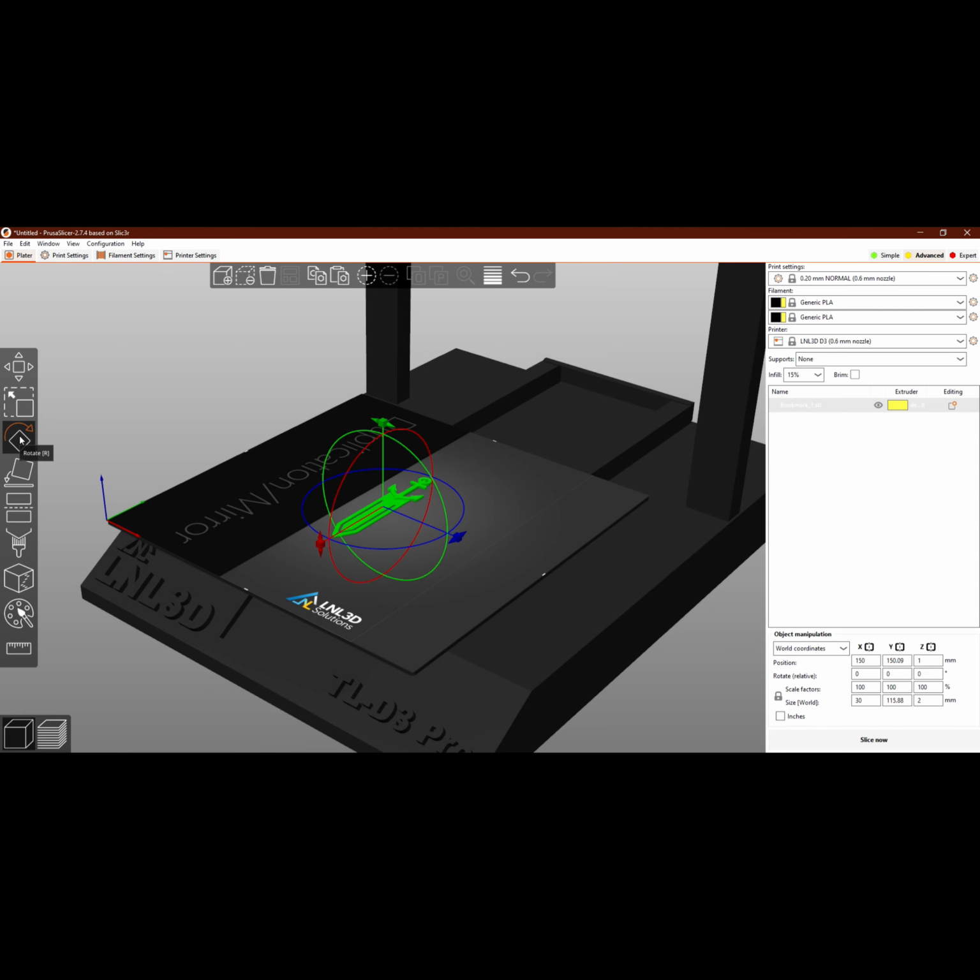There is a Paint on Supports feature which allows you to add supports manually, seam painting to manually adjust the position of seams, an option for multi-material painting, and a measuring tool to check the distance between 2 points. In the top right corner, you can add automatic supports, either everywhere, for support enforcers only, or only on the build plate. You can change the density of the model by adjusting the infill percentage, and you can add a brim that prints a first layer surrounding each print for more stability. Here you can also adjust the layer height and filament type.